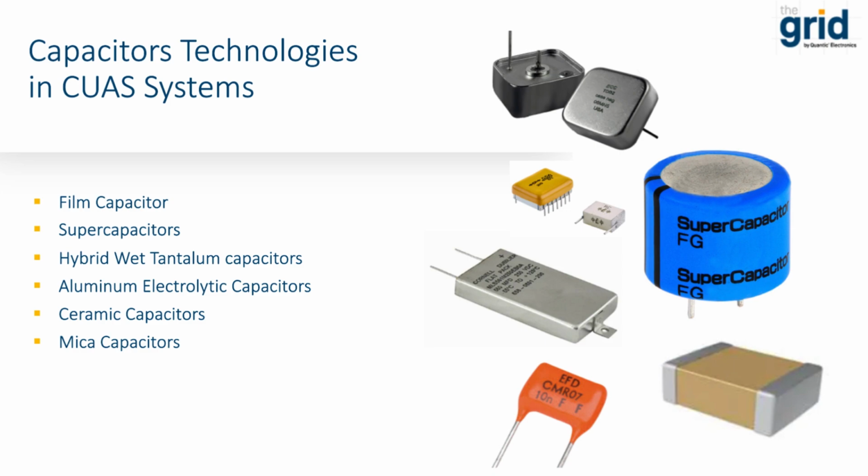Mica capacitors are commonly used in communications, radar systems, aircraft power supplies, and other military applications. They provide stable performance without cracking or piezoelectric effect, ensuring reliability in critical systems. Metal-clad mica capacitors utilize metal-clad technology. These capacitors run cool due to their silver-plated brass case that acts as a heat sink. They can carry high current with ultra-low resistance, making them suitable for RF and microwave power applications.